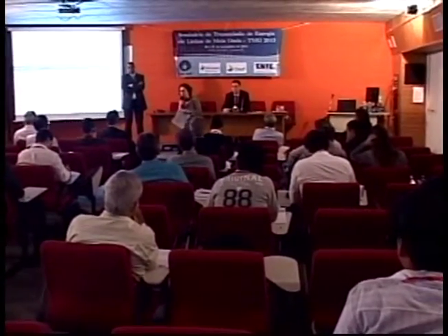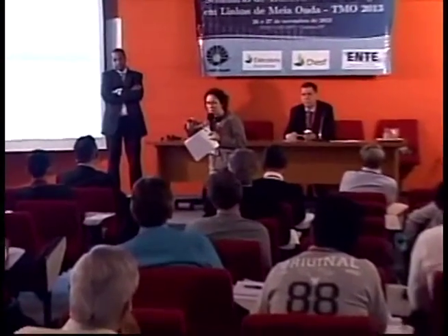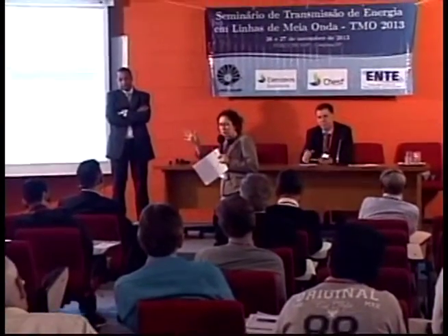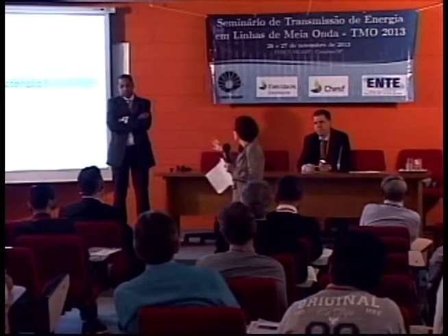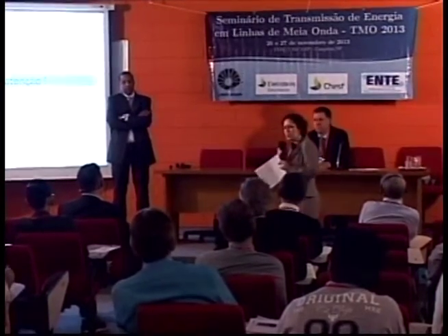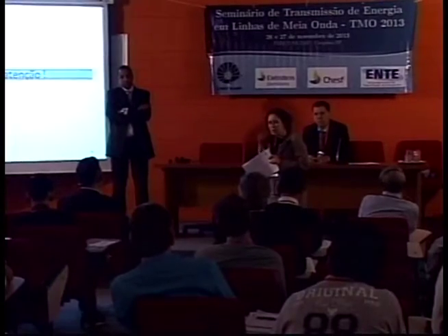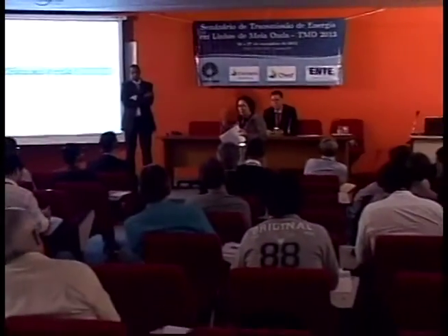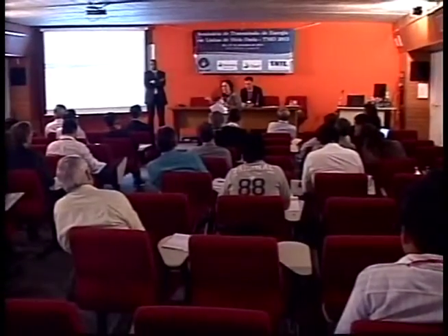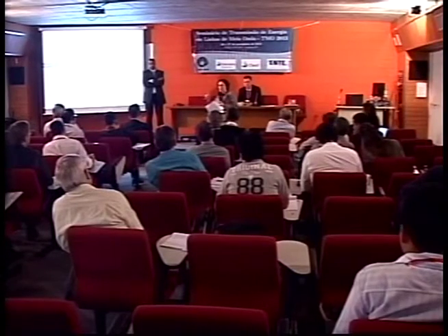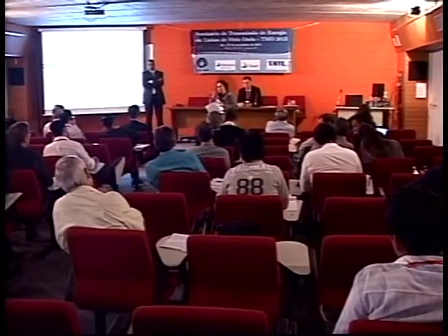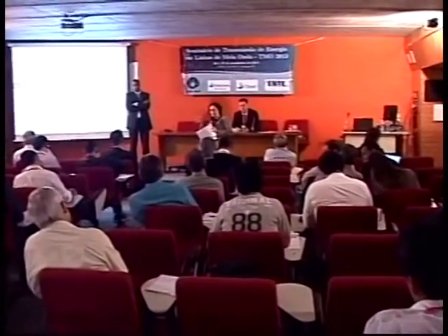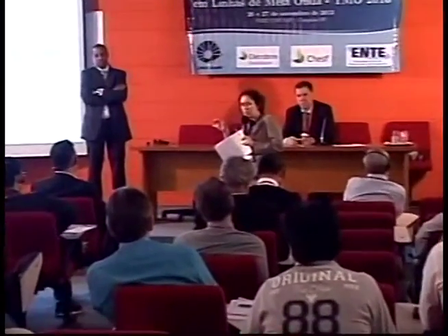João, in this stage of the work, we still have not gone into the details of the substation. We started with 2 kilometers, we have a terminal fault, and what we are seeing is that it was always less severe than the existing line. So that's what we were basing ourselves on. Both simulations, for terminal and kilometric, were less severe.